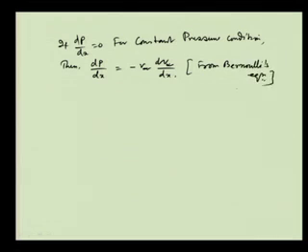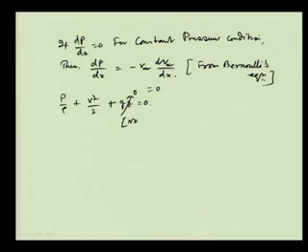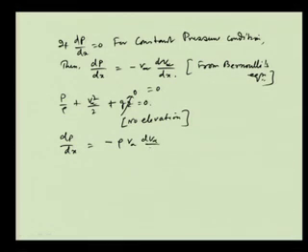What is that? And that is equal to 0. What is that? We know that Bernoulli's equation says that P by rho plus V squared by 2 plus g z is equal to constant, and with no elevation, this part is 0. Then we get dP by dx is equal to minus rho into V infinity, the velocity in the free stream conditions, so V infinity dV infinity by dx.